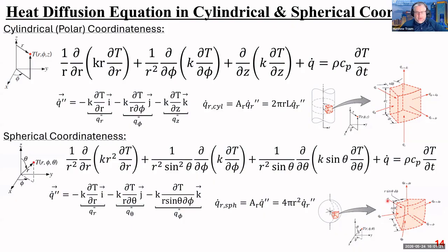And then we look at the temperature entering and leaving on each of these faces relative to the face in the previous or the same direction. And then we allow for a generation term and we allow for a temperature change with respect to time, an energy storage term, right? Time derivative term.